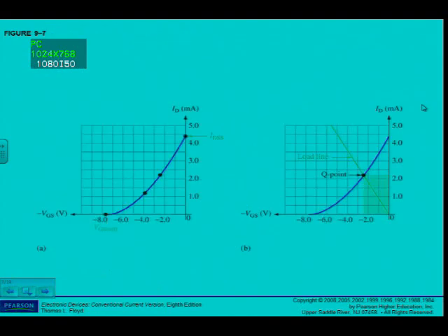Remember, you know how to do this. And remember, self biasing, I know how to. I have to determine when ID is equal to 0, then of course VGS is also equal to 0, and the other one was where ID is equal to IDSS. Then I had to determine that value so I can plot the second point, connect the two lines and get the load line. Remember to make sure that you know if you're working with a self bias or a voltage divider biased circuit. Anyway, let's have a look at example 9.2 in the textbook.